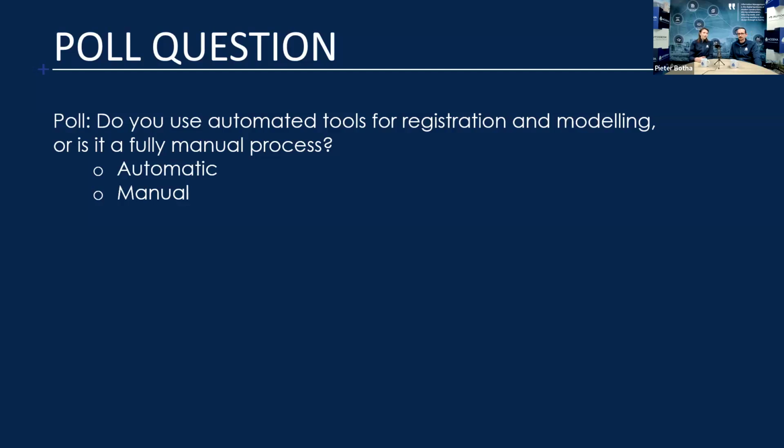Yes, you can. You can do that manually by checking your building model against your point cloud data set, or you can import that into Navis as well. There is also clash detection specifically built in for point cloud modeling. Definitely possible to do that.